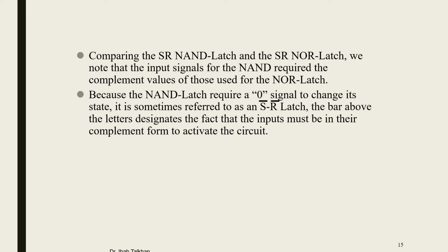Also, when comparing the SR NAND latch and the SR NOR latch, we note that the input signal for the NAND requires the complement value of those used for the NOR latch, which means they are opposite to each other. Because the NAND latch requires a zero signal to change its state, it is sometimes referred to as an R bar S bar latch. The bar above the letter designates that the inputs must be in the complement form to activate the circuit, and this is what we discussed when we talked about the NAND gate previously.